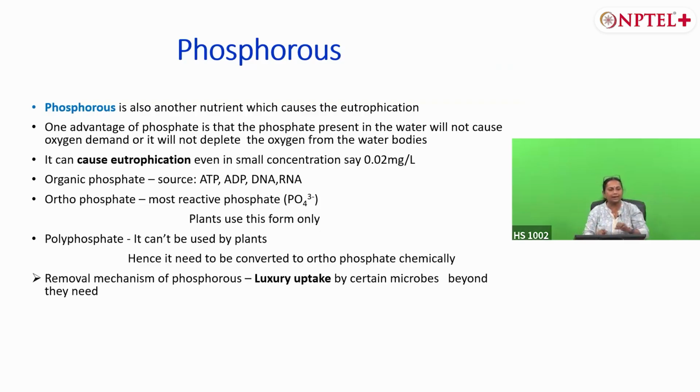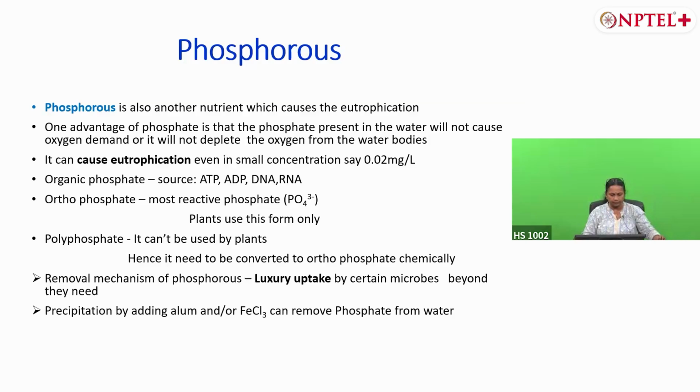Those small globules you can see are excess fixation of nitrogen that they are storing. Similarly, for phosphorus, there are certain microorganisms that can accumulate phosphorus much more than whatever is needed for their cell synthesis and all. That is known as luxury uptake. Only certain microorganisms, under certain conditions. So that is the way we remove phosphorus biologically.